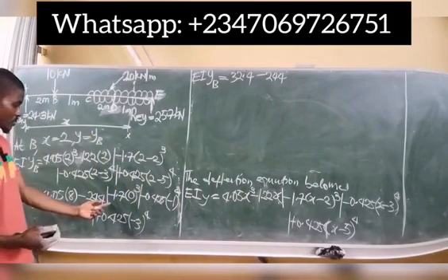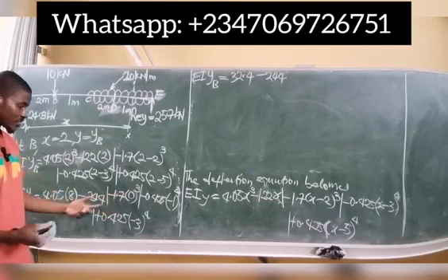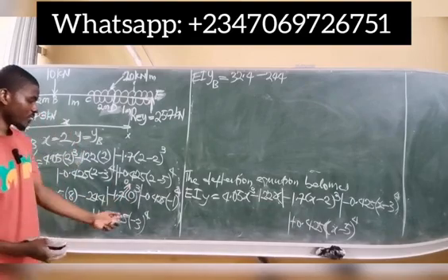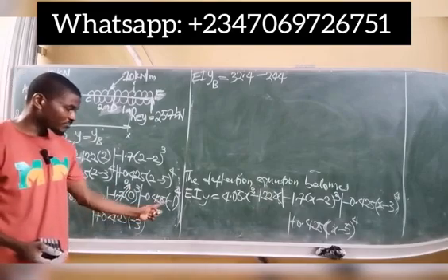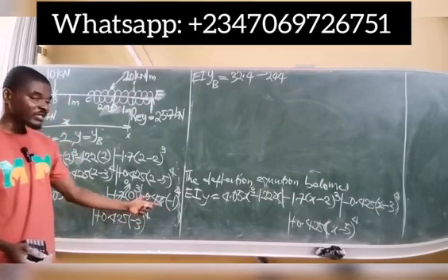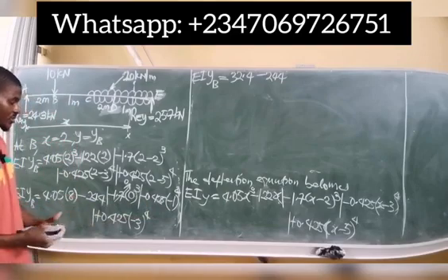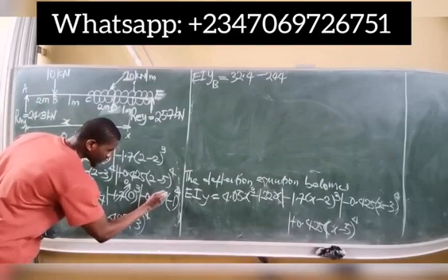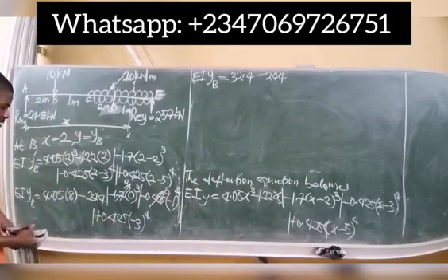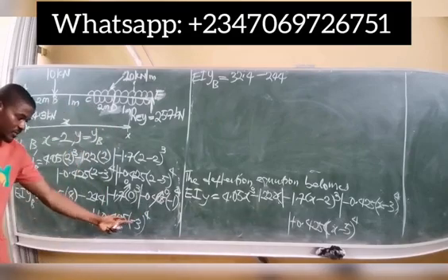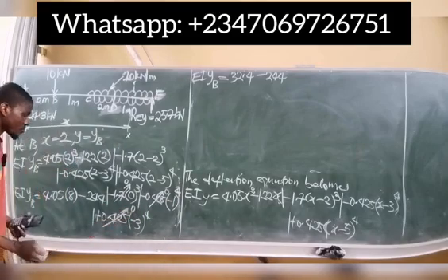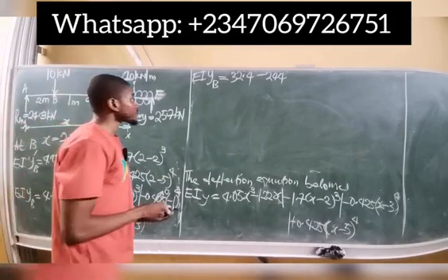We have here minus 1.7 times 0. Of course, everything here is 0. Also, we have here minus 0.425 times minus 1. So far, we have a negative value in the bracket according to Macaulay's theorem. When the value in the bracket is negative, of course, it is 0. Same thing happens here. We have minus 3 in this bracket, so it's negative. Automatically, everything here is 0. So we simply have these two values.